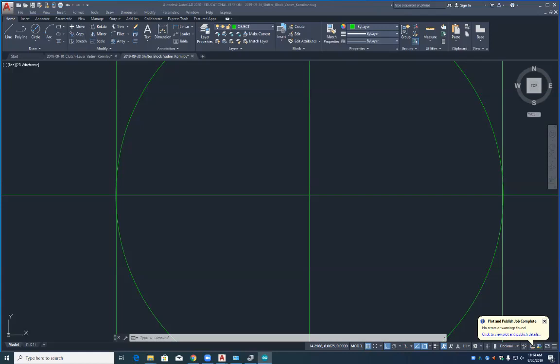So what I'm trying to do is, you learn these now, try to use these commands now in drawing your object. Your whole concept in here now is to get faster at what you're doing. Now, a couple of things. How do we repeat a command? Space bar. You enter a line, draw a line, space, space, draw a line, space, space, draw a line, space. Does that make sense? That's all I'm doing. That's why I'm so much faster. That's what I want everyone in here to do. Try to get those space bars. Use that finger and hit that space bar to repeat commands.